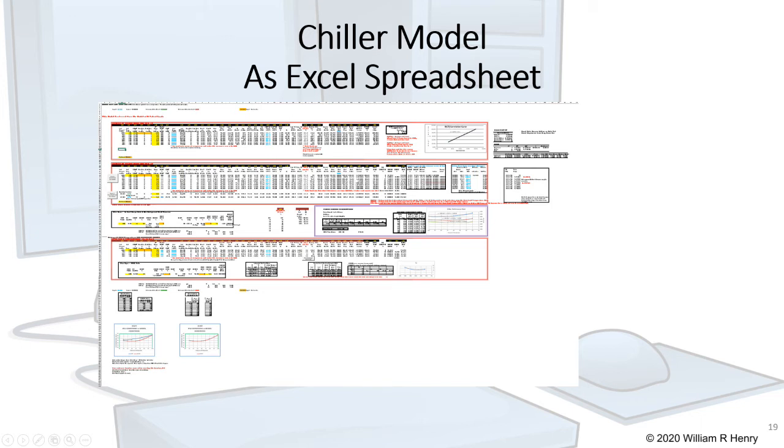Calculations are based on thermophysical properties, flow dynamics, and system losses. The calculations include my unique patented method to characterize and implement refrigeration mass flow limits. This customized chiller model can be evaluated with various combinations of condenser water temperatures, chilled water temperatures, and load.